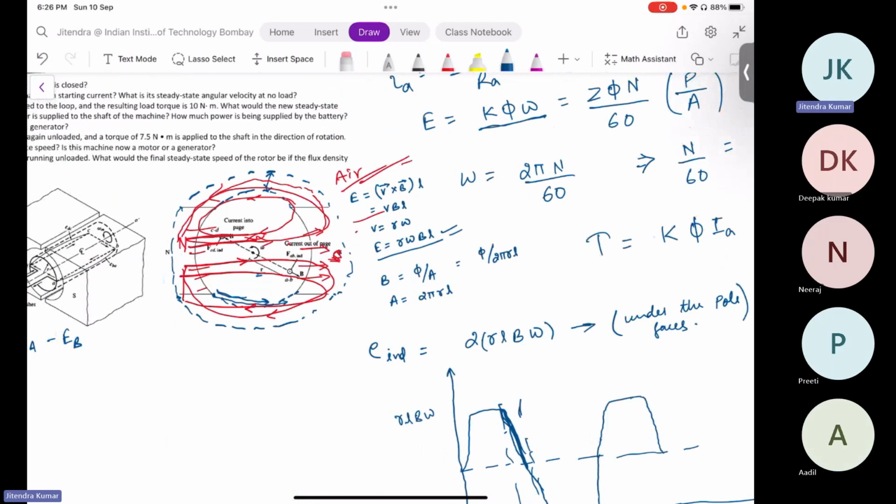number of poles. Number of poles is not what you physically assign. You just place two kind of magnets and that will create two poles. That is fine. But the number of poles is also how many flux loops are generating in the machine. If this machine is not completing that many loops, then there is no point of placing two poles physically.